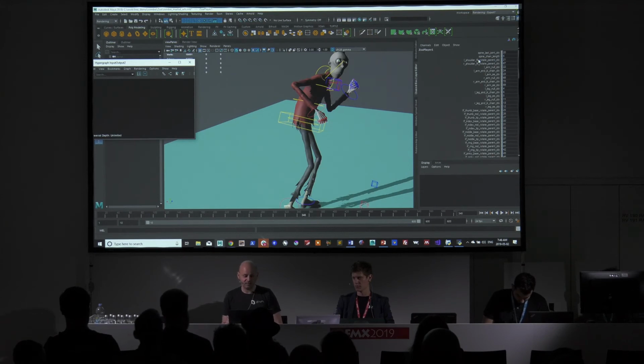In the software that's currently available to you right now, if you do want to run dynamics, you're not limited to doing a full anatomical setup. You could do something much simpler if you just want to add jiggle to something. We have a goaling attachment, which allows you to goal your simulation to a traditional rig, if that's what you have, and then you get the oscillations that you'd expect from the dynamics. If you want to bake it down to something which you can interact with, as far as commercial productization goes today, I would probably use the quasi-static solver, or run it in dynamic mode with your frame rate at like 1 frame a second, so that the dynamics settle, and then you could bake those out as shapes and add them in as blend shapes into a traditional rig.